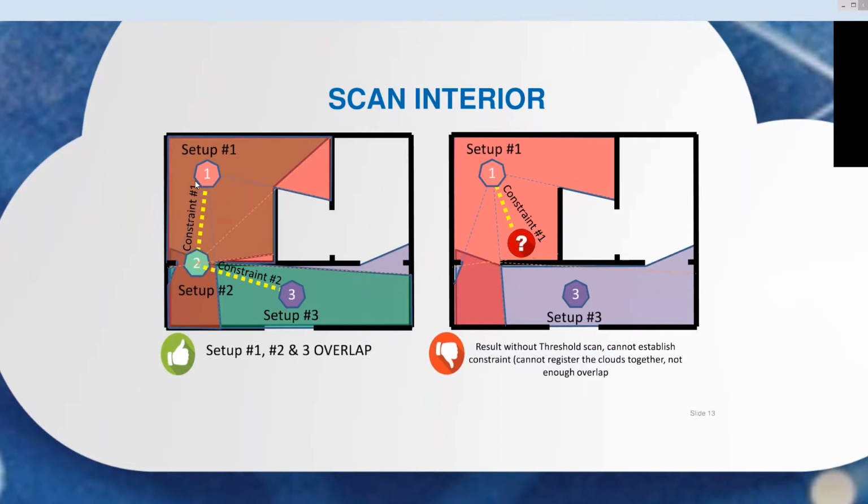In this instance, scan number 1 and scan number 2 have to have some kind of overlap. You can see where the shading of the red and the other colors overlap each other. That's how they share the information, and that's how auto registration happens. If you don't have anything recognizable by whatever program you're using to register, then it's not going to register together.